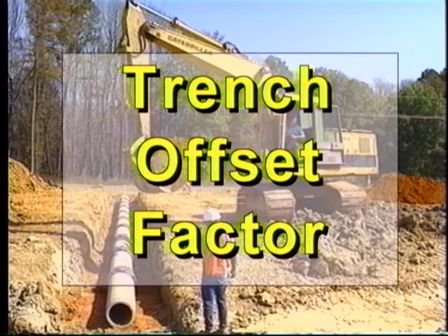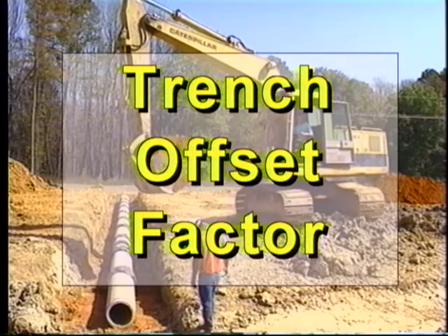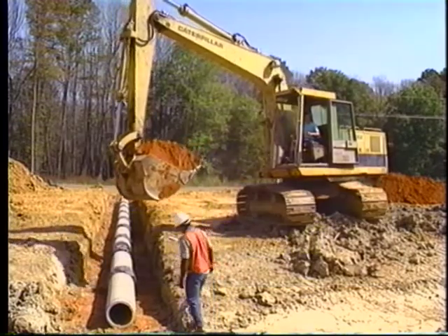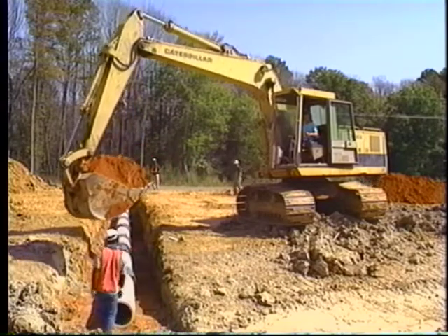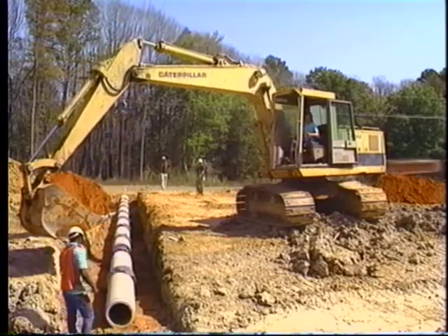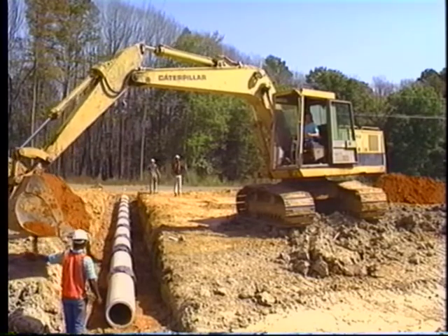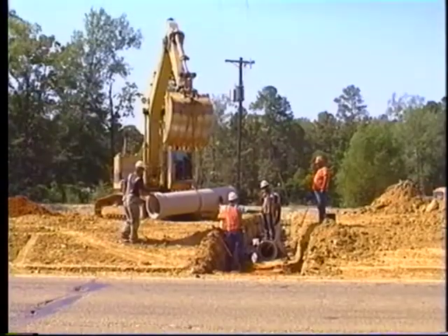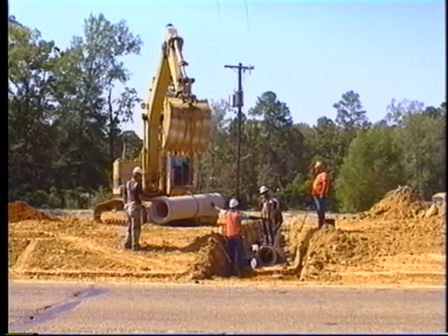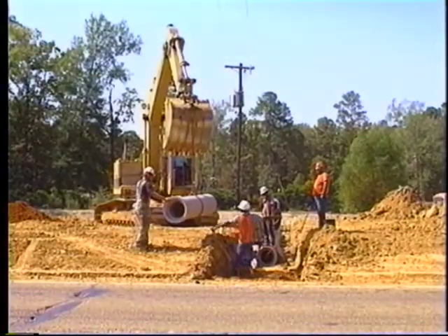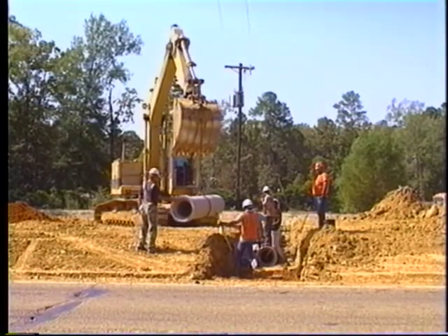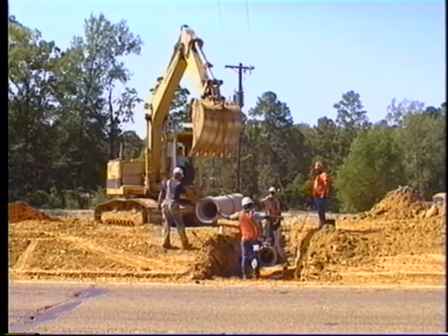Trench offset factor. As a result of radiation echoing from close vertical structures, the walls of a building, trench, or ditch may adversely affect density and moisture counts. As we mentioned previously, when a test is to be performed in an area with less than 1.8 meters or 6 feet of clearance from close vertical structures, the trench offset factor must be used to obtain an accurate reading.